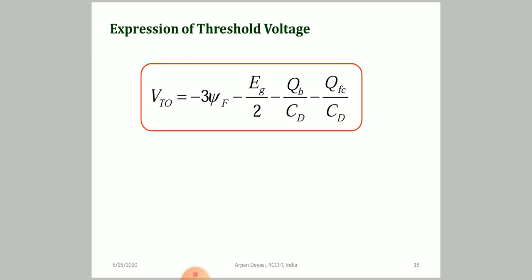That's not my target. My target is what the functions are that the threshold depends on. Look, it depends on the dielectric capacitance. So that's simple, oxide capacitance or whatever dielectric you are using. It depends on the bulk charge. Obviously, for the capacitance you require the bulk charge.